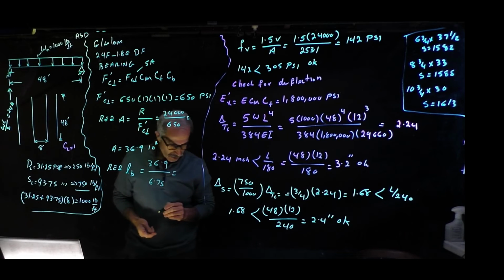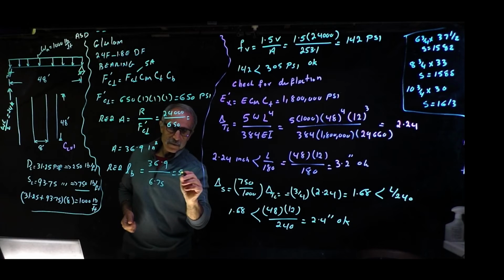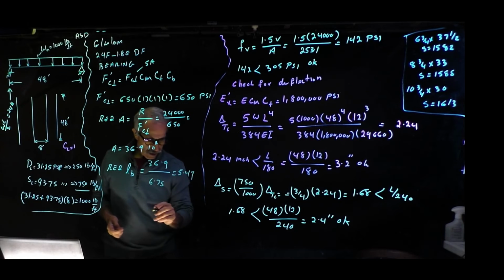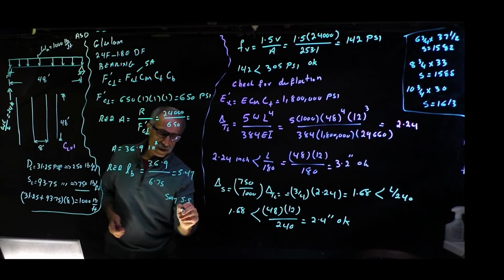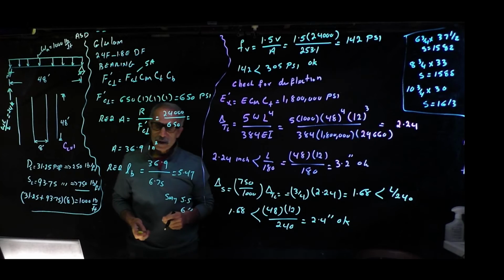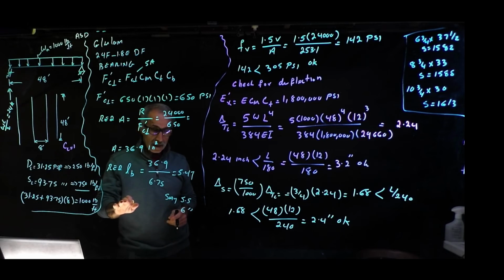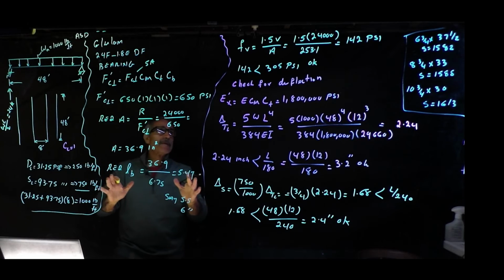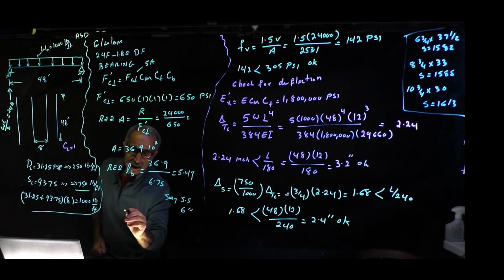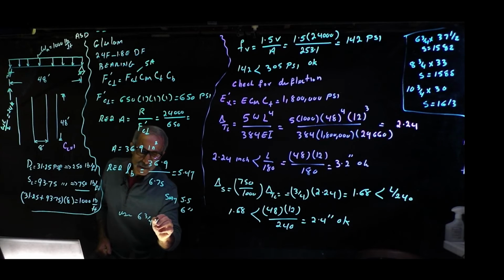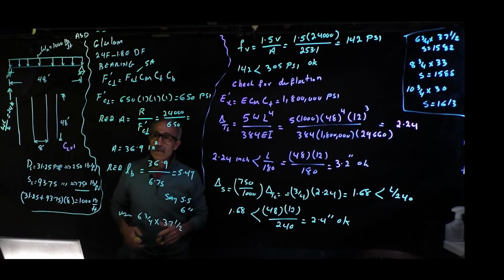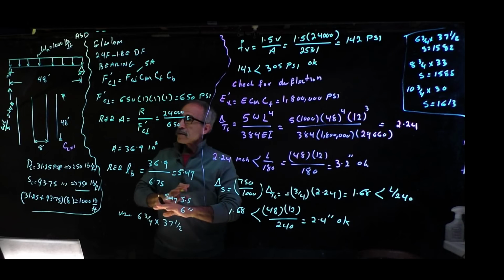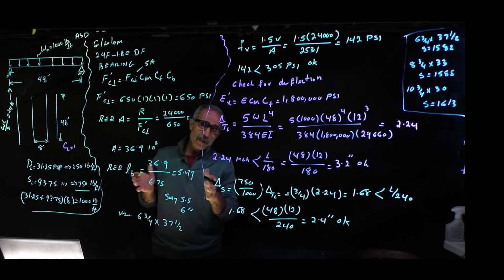So that is equal to 5.47, say 5.5 or 6 inch. It's up to you. So that's our bearing. So now we're going to say, okay, this beam is okay, designed for use 6 3/4 by 37.5. If you use this beam, it's completed. It will stand that load.